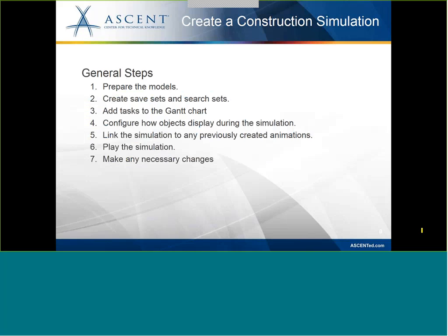Specifically, when it comes to setting up a Revit model to come in and show that construction simulation, in Revit a wall is all one object. So we show you and walk you through the steps to split that wall out, so that maybe you get your studs up first, then you put your sheetrock on, and then you go back and put your bricks on the exterior. You can have each of those individual layers show up when they really would show up in the construction field.